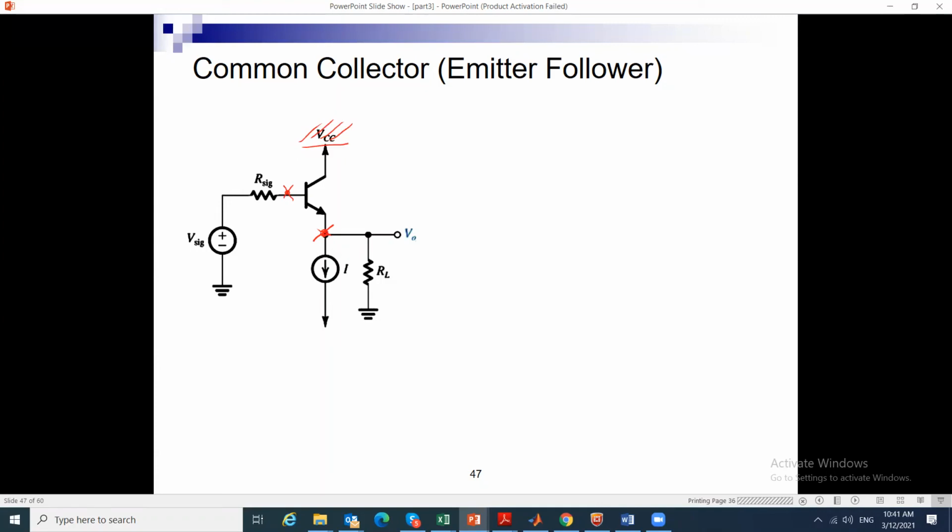Now, the only difference in the emitter follower is that if we want to find Rout, it is simple because I will ground node Vn, and Vn is at the end of Rsig. Okay, Rout is when Vn equal to 0. I remove RL, this is ideal. I will look up, I know how to find this equation.